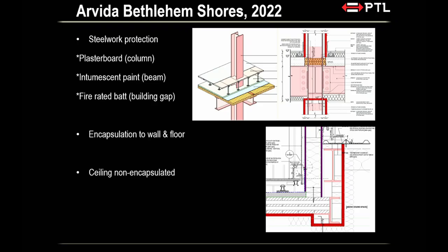Now the only issue here is for the steel column to go through, you've got to create a notch in your floor. So you've got to cut a hole in your CLT floor, and it's an I column, so there's a lot of gap. So those gaps will still have to be filled up because, why? Because in the event of a fire, the ceilings fall off, right? The beams have all intumesced, right? The column, you still have board protection, and some part of it where the beams intersect will also intumesce, but then you have all this gaping hole, right? So what we ended up fixing is a fire-rated batt that is cut to cover up the remaining space between the columns and the floor, right?